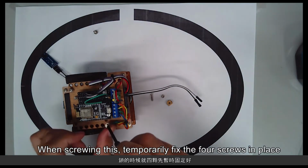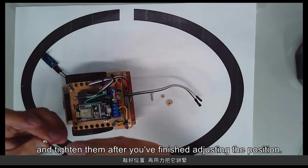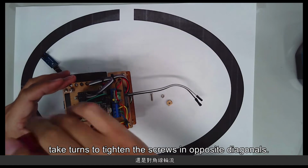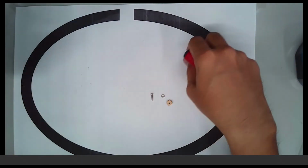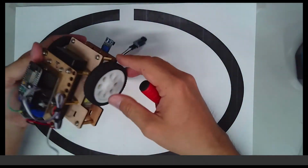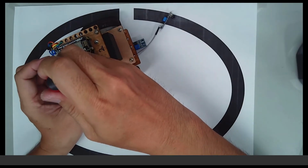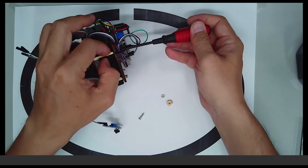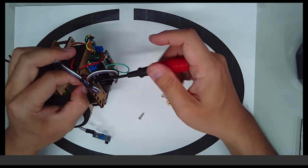When screwing this, temporarily fix the 4 screws in place and tighten them after you finish adjusting the position. When tightening, take turns to tighten the screws in opposite diagonals. Don't screw it all at once and do it slowly. This screw was left on top. You can take a look from the side to help align in place, then tighten it.